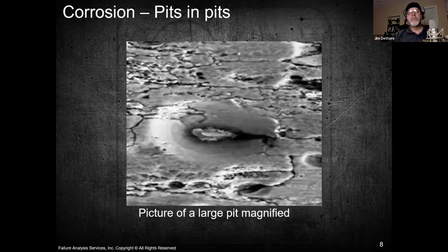And you can do some of that visually, but when it comes to the folks at ASM, American Society of Metals, they tend to be the authority on most of this stuff. They'll say there are rapid corrosion tests and slow corrosion tests, and basically they're taking a similar piece of the material and they're either elevating or reducing temperatures, trying to get the corrosion to accelerate, and potentially wetting it with the different electrolytes and stuff like that. So there are tests that can be performed, but they take a while. Even the rapid test is not as rapid as you would think.